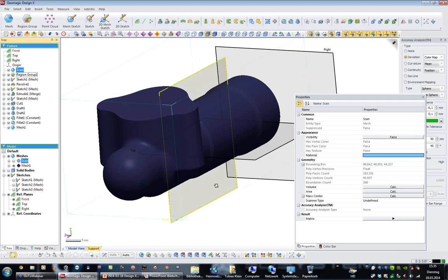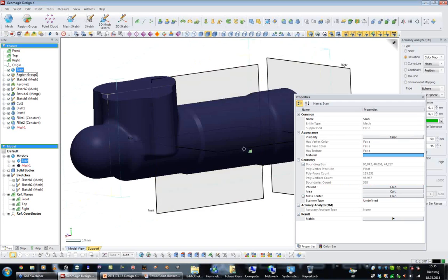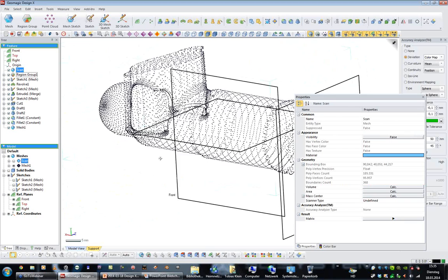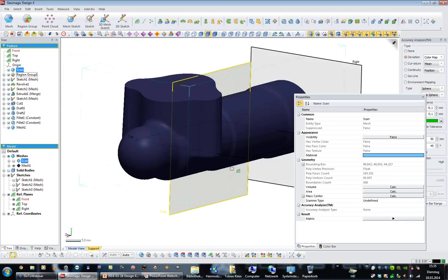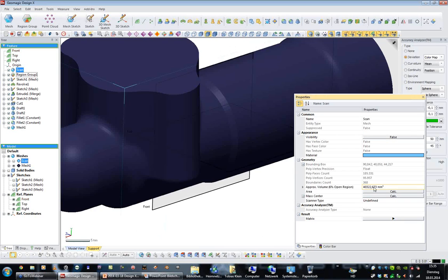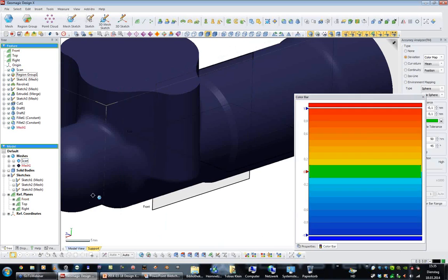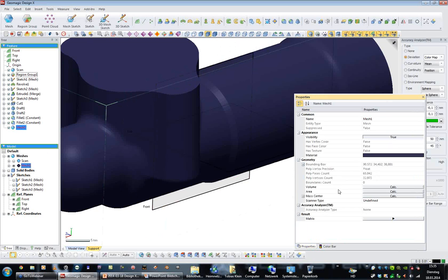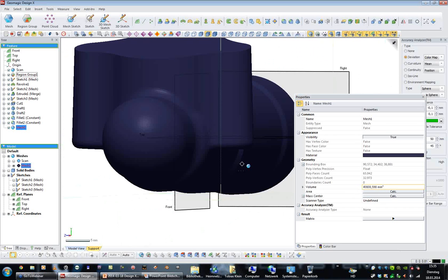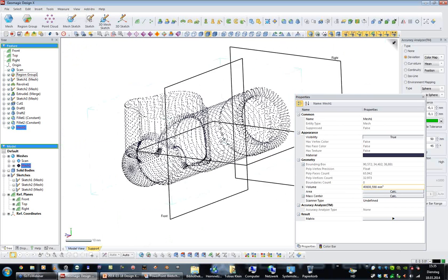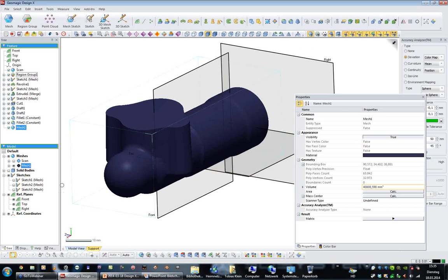And if you take this other mesh, this is generated from the CAD data which we created just before. This one is exactly, I picked the wrong one again. So this one I need. This one is exactly closed. This is watertight, and it shows the exact volume of the mesh. So the mesh is watertight and it is printable. No material is flowing out.